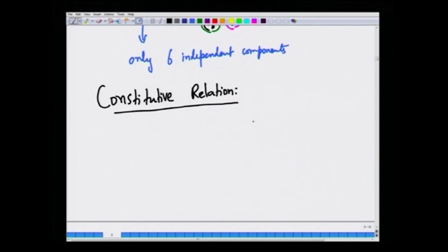Firstly, let us take a very simple system, that is, flow happening between 2 plates, x and y. The bottom plate is stationary, static, and the top plate moves with a velocity v. So, you will have a velocity profile that looks like this, in between the 2 plates.